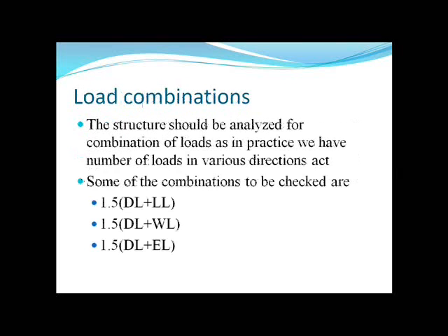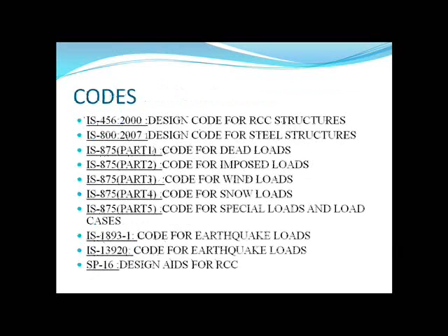Now coming to the load combinations, a careful combination of various loads has to be considered. The structure has to be analyzed for combination of loads. Some of the load combinations can also be excluded, such as wind load and seismic load cannot come at the same time. Slide shows the codes.